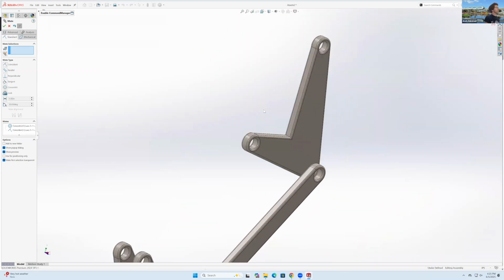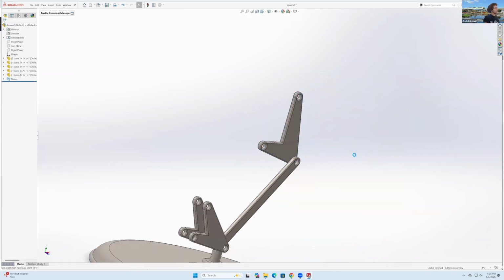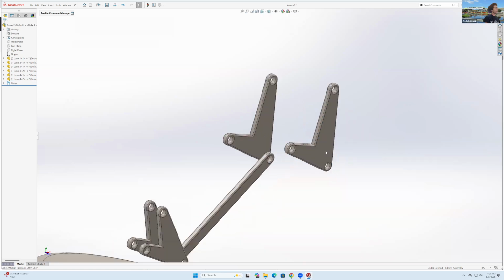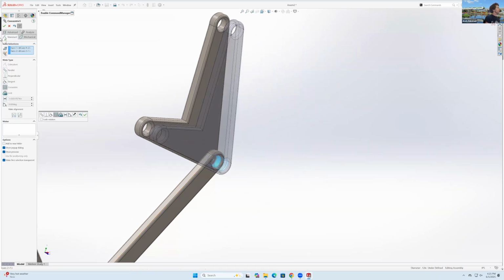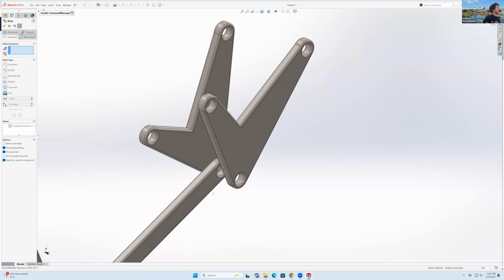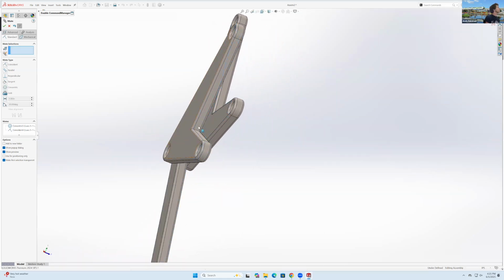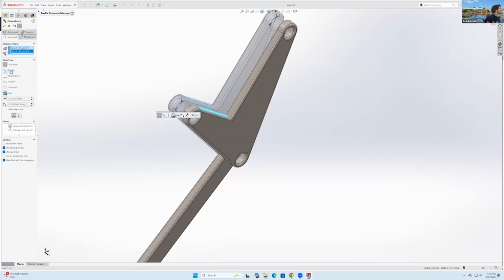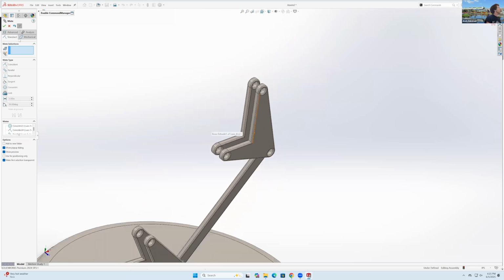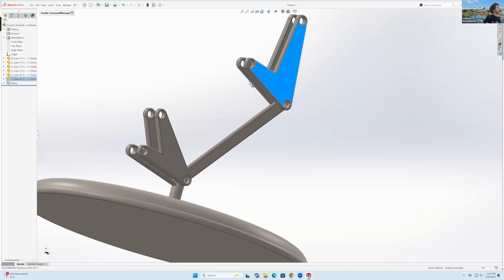And then I can click on Luxo 4 right here, Control C, Control V, and I'm gonna lay it out right there. And then mate, I'm gonna do the exact same thing. You could also mirror parts in assemblies, but I don't like doing that personally. It tends to cause trouble, and at least in Siemens, it caused a lot of trouble. So then I'm gonna click on these 2 faces and I'll make them parallel to each other. So all of this means is that now, not only this can move, this can move too.